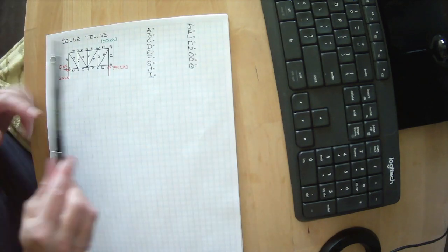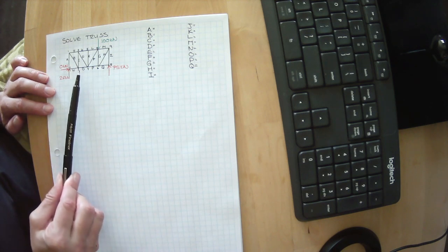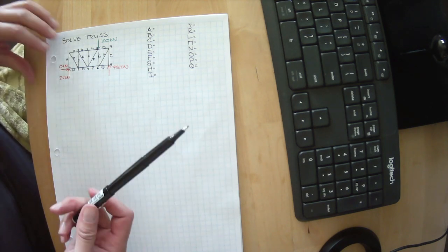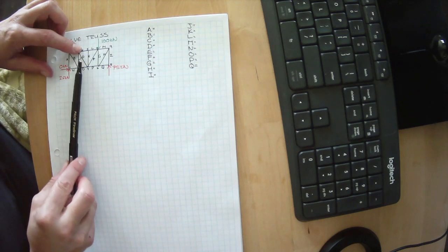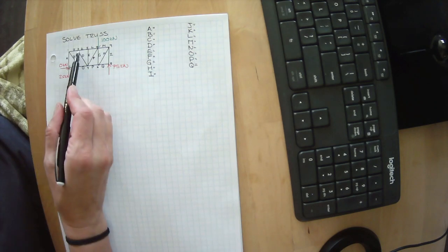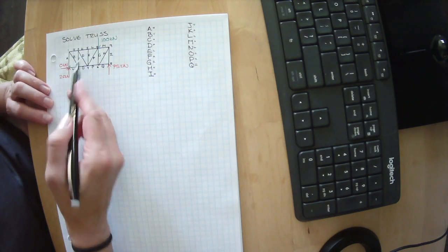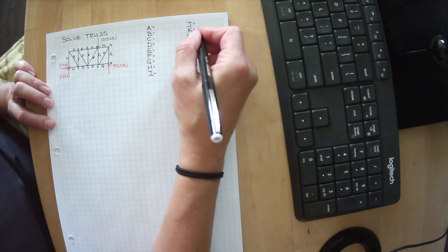Well, check it out. We originally cut right here. We cut through K, D, and O. We called them A, B, and C because we didn't know what we were doing, but we cut through K, D, and O. And we established that this member here, that is K, was actually 33 kilonewtons of compression. So let's go find our K.